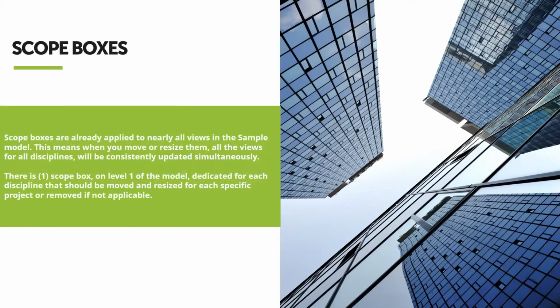And this is the important thing with this pack, and I think I touched on it earlier. Scope boxes are applied to nearly all the views in the sample model. If you change the scope box's dimensions, you change its height or its X and Y, you're going to change all of the views that are set to that scope box. And so that's why we do this. We can take that box, move it to where our actual project is. Once we've cut our template from the main file, we can move it to where we want it, and just keep going. We can get to work. Everything's there. It's all linked in. We're ready to go.